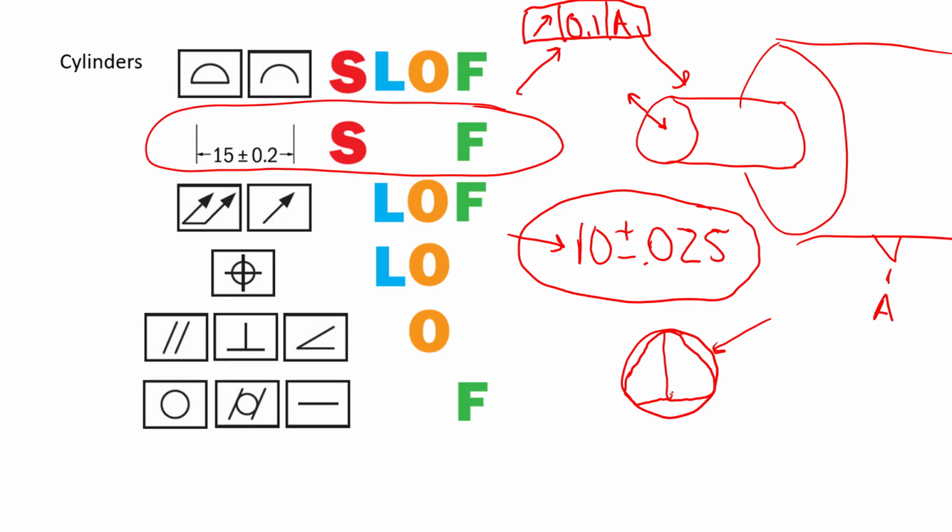And then every 2-point measurement, due to rule number 1, would have to be larger than 9.975, right? So it has to live within that. That is controlling the size and the form, in this case, is rule number 1. The runout, though, the 0.1, is controlling now really this axis of 0.1. So this 0.1 is being controlled by the runout.